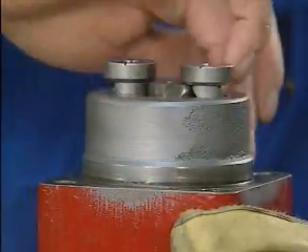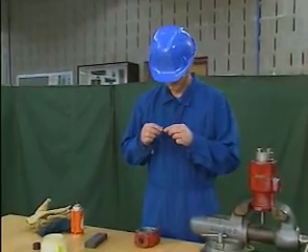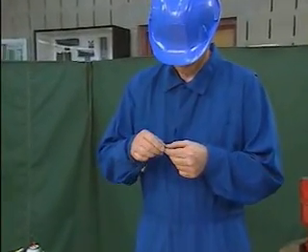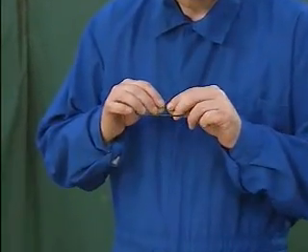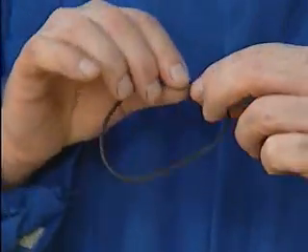The sealing surfaces are in good condition, so the mechanic then checks the O-ring selected for this application to make sure that it's free of cuts or other damage. If the O-ring is damaged, it may not seal properly and should be replaced.